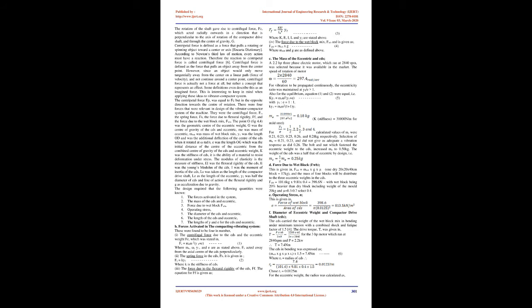Centrifugal force is defined as the force that pulls an object away from the center point. However, since an object would only move tangentially away from the center on a linear path, by force of velocity, and not continue around a center point, centrifugal force is actually not a force at all, but rather a concept that represents an effect. Some definitions even describe this as an imagined force. This is interesting to keep in mind when applying these ideas to the vibrator compactor system. The centripetal force Fp was equal to Fc but in the opposite direction, towards the center of rotation.